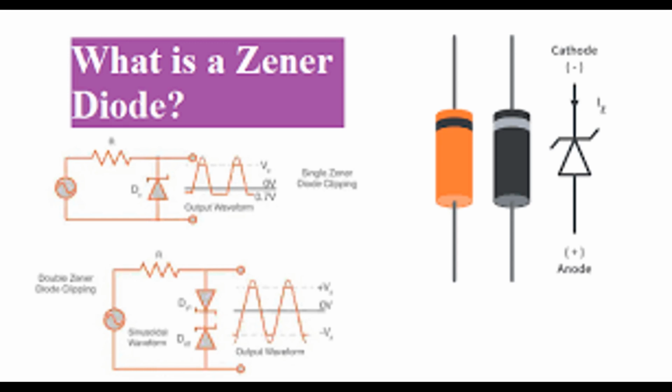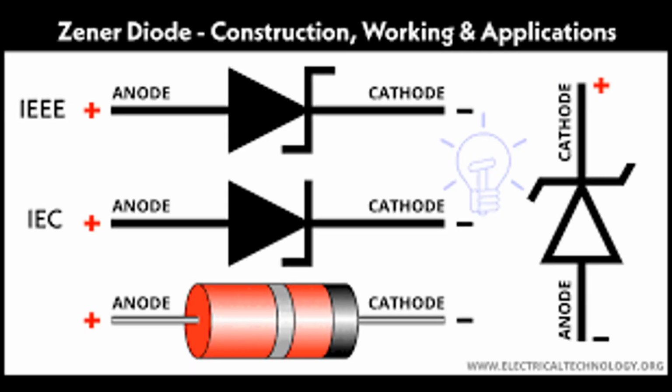Overview. In AM, the amplitude of a high-frequency carrier signal is varied in proportion to the instantaneous amplitude of a lower-frequency information signal, such as an audio signal. The objective of demodulation is to recover the original information signal. Diode demodulator, envelope detector. Diode-based demodulators, known as envelope detectors, are commonly used in AM demodulation.